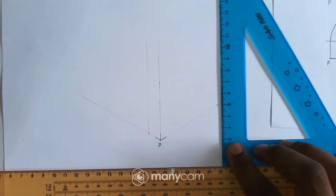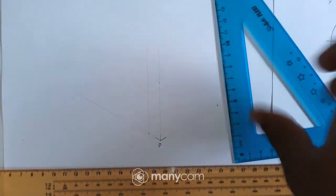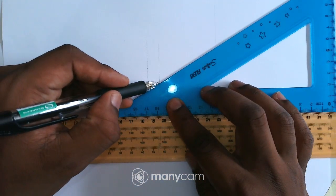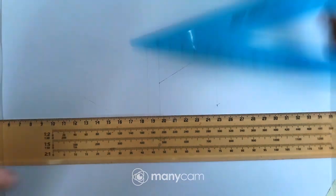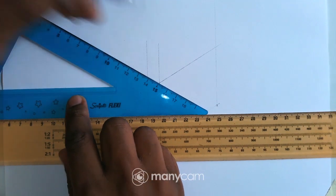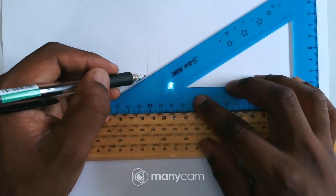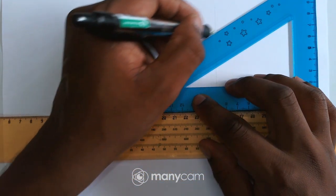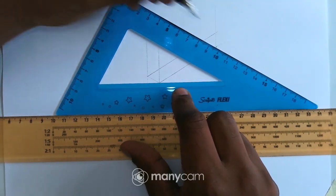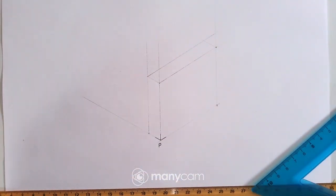Draw a vertical line there and a vertical line on this point, and then for this point just project it to the right and to the left. Then I have to draw the top section just like that, and then this point there, just like that. Now I do have my isometric block.